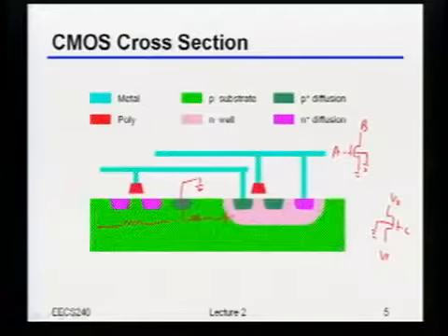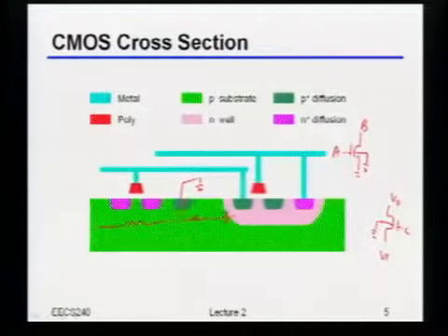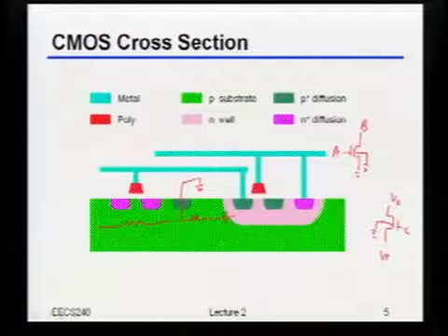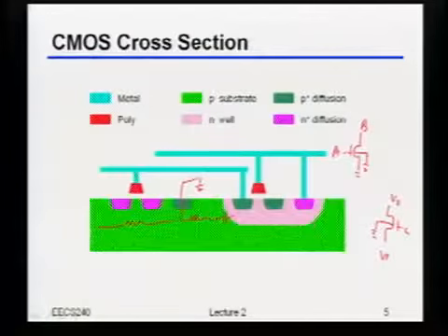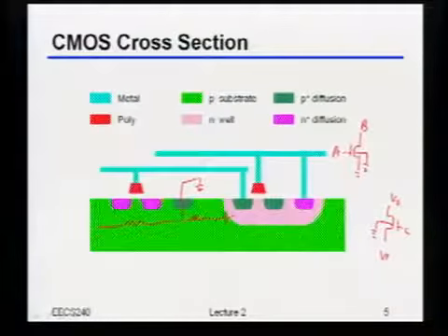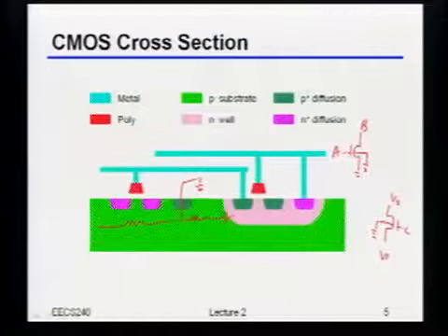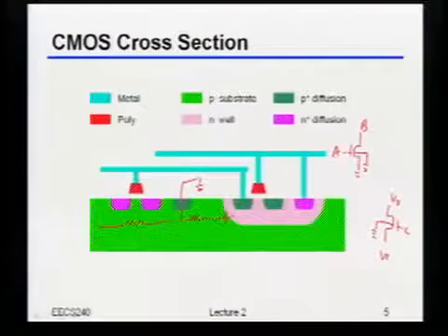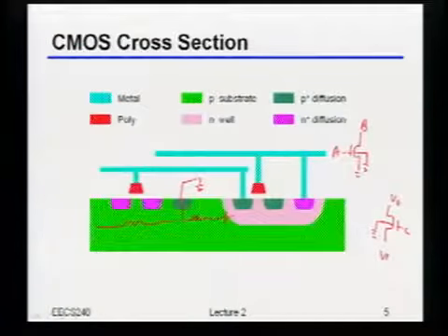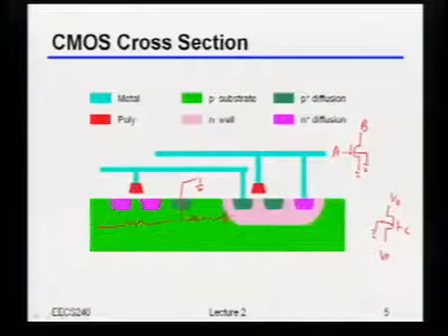And again, the only reason I mention this is because a lot of times in analog, the thing that comes and bites you is the thing that's not in your model, right? And substrate, really classic thing that's almost never in your model. In fact, I could almost argue that PMOS transistors are in some sense even worse from that standpoint, because every time you instantiate a PMOS transistor, there's usually some components there that in real life exist, but SPICE never actually takes care of. So anybody have an idea which components I'm referring to or what they're related to?